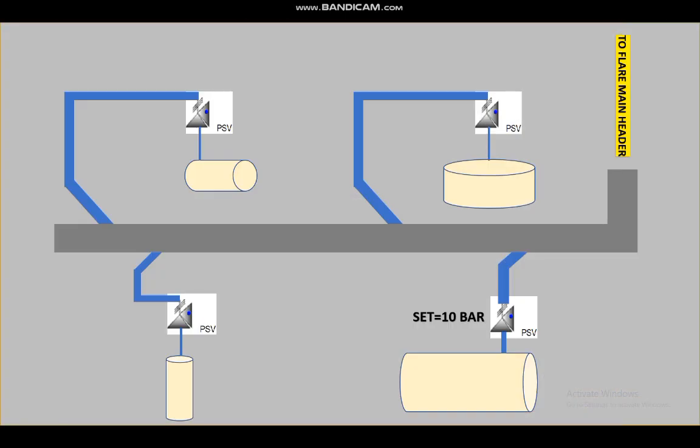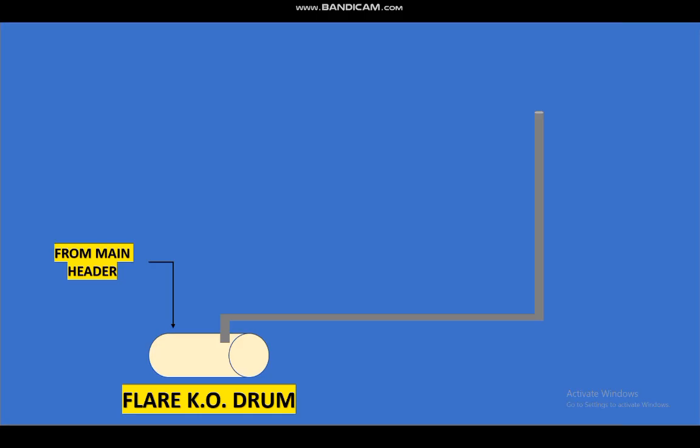Well, let's start with PSV. You can see the vessel at the bottom right-hand side of the figure. Its pressure reached the set pressure of the PSV. Once that happened, the PSV opened and released the excess fluid into the flare network, and the vessel pressure reduced to, say, for example, 8 bar. In this way, the PSV protects the vessel from potential damage. The pipe forms the flare network that transports the relief fluid from the PSV to the flare stack. The fluid is then safely burned at the flare stack, converting hazardous components such as H2S and CO into less harmful components.